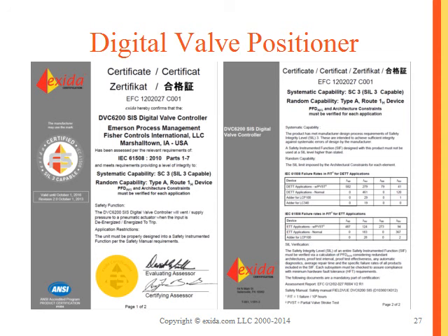Can the digital valve positioner be used non-redundant in SIL 3 functions? Most likely not. I haven't run the calculations. Most likely I will need redundancy, but I can use it in SIL 3 level applications because the development process and the quality system that the manufacturer uses meets the requirements of SIL 3. So we have the specific product identifier here, the manufacturer, the standards and assessment levels. We have the safety function defined. On the back we have the failure rates, and we have the supporting documents. So here you see the safety manual, you see the assessment report, the unique identifier of the certificate. So this one looks just like something I just described.